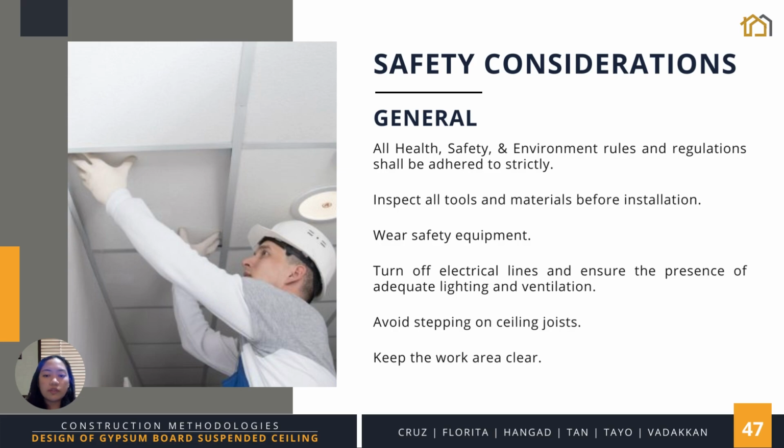This includes a safety helmet, shoes, belt, vest, goggles to avoid eye irritation, and gloves to minimize skin contact with materials. Since electricity is a major hazard, turn off the electrical lines before installation. Additionally, adequate lighting and ventilation shall be ensured, as lighting is generally poor in ceiling spaces.